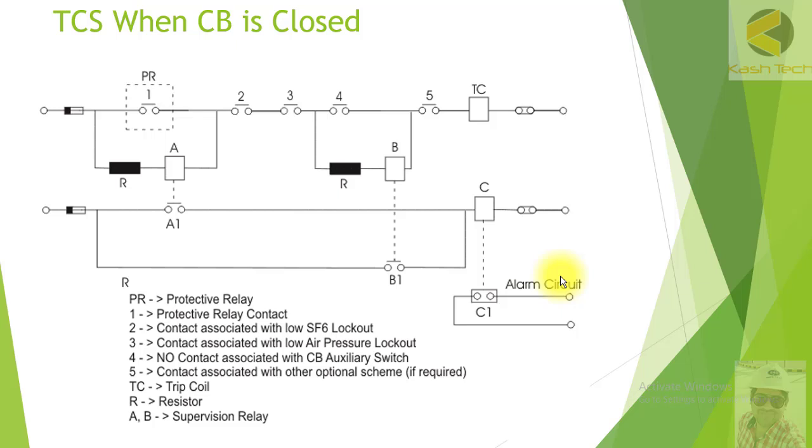I have explained these possibilities in closed circuits, same are also valid for the open circuit. So this is a very basic diagram. Later I will show you how you can read this. If the concept is clear in this ladder diagram, then later in schematics we will see how to check the drawings and how to troubleshoot.